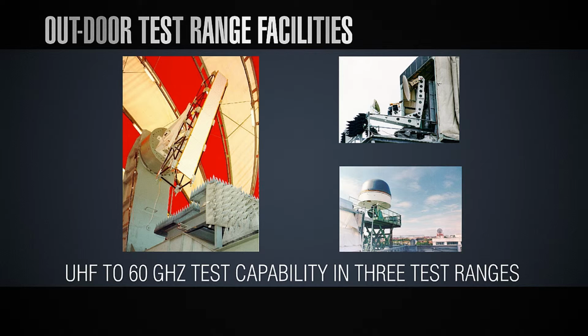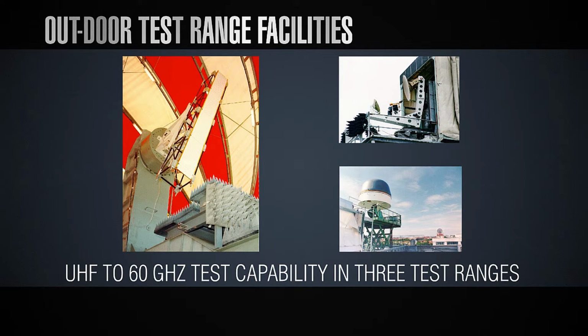This can be a problem for satellite antennas because satellite antennas have to be realized under certain quality conditions, so the outdoor environment can be dangerous, so you have to be careful, maybe realize some protections. You see that there were sort of balloons transparent to the electromagnetic field. But this approach is still theoretically the most valid because you are really testing the antenna in the actual operating condition. You are far away from the antenna. You can assume that what you measure is really the far field of the antenna.